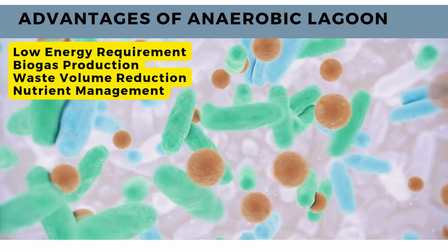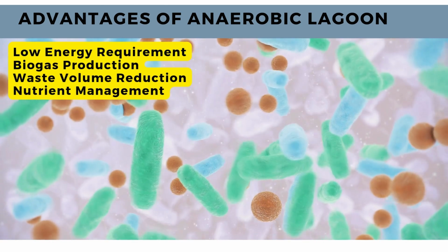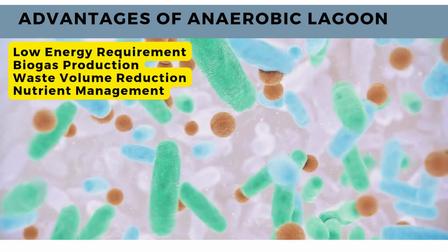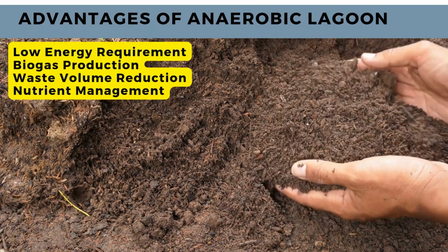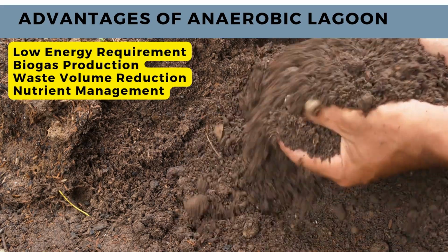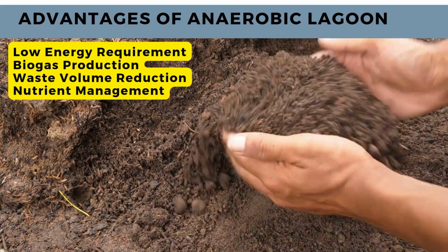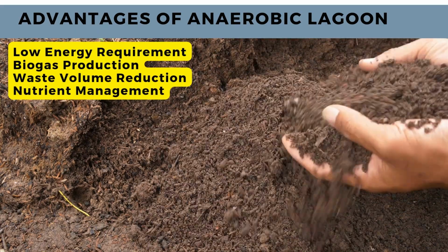One of its advantages is waste volume reduction. Through digestion, organic material is significantly reduced, lowering the volume of sludge to be handled later. It is also good in nutrient management. Lagoons can help manage nutrients like nitrogen and phosphorus, which can be valuable if further treated or used as fertilizer.